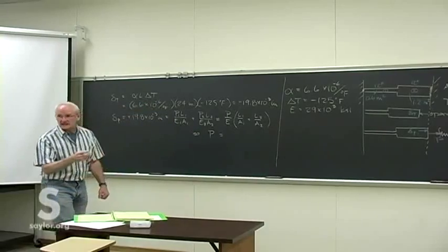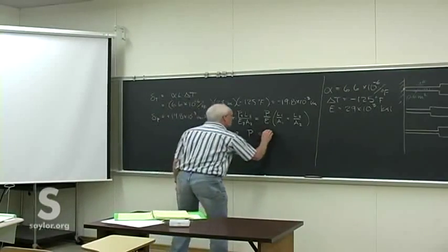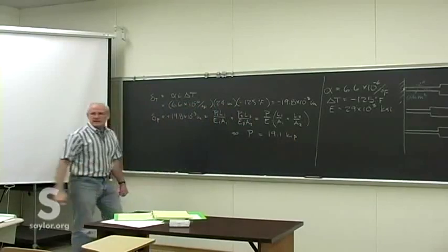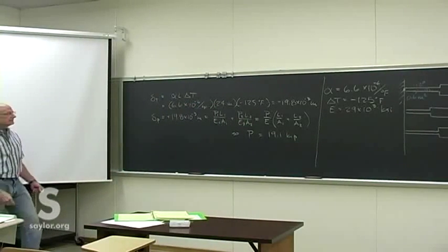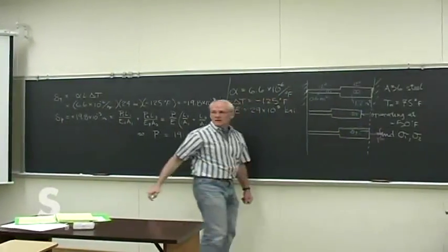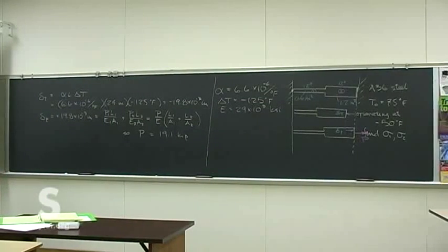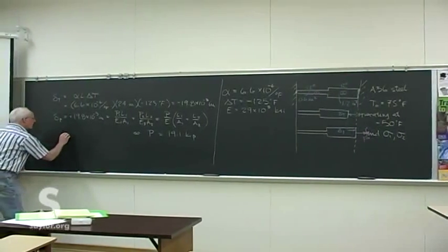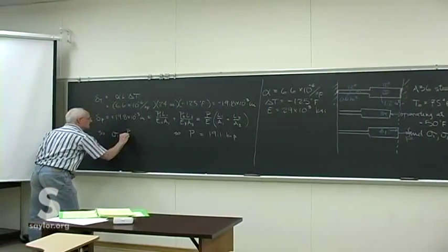Well, we need that to find the stress. So this turns out to be 19.1 kip. The tensile force the piece is experiencing in order to keep it at the same length despite this rather extreme change in temperatures. And then from that, we can find the stresses in the individual pieces.